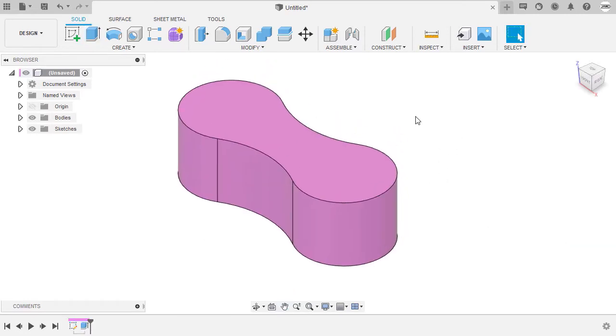So notice my model has a different color. It is because at the bottom right, component color swatch is currently turned on. And to return to its original color, all we need to do is press Shift and N, letter N.